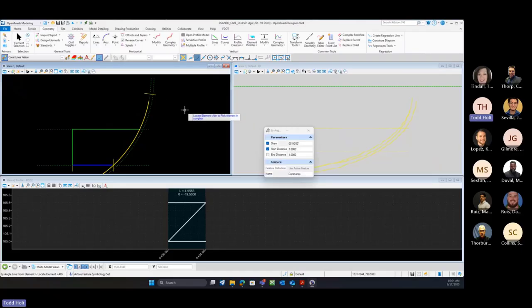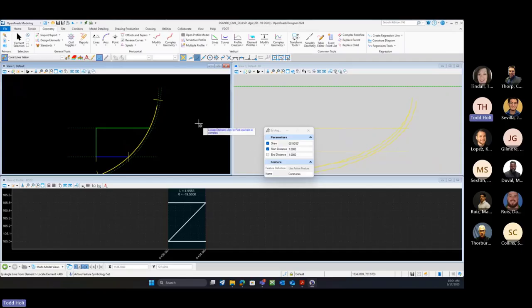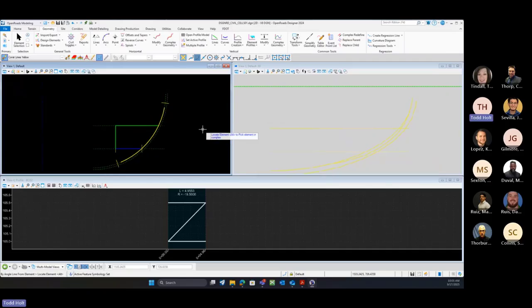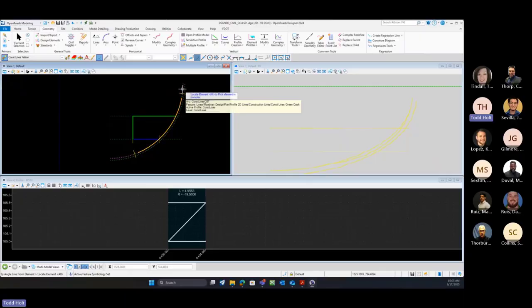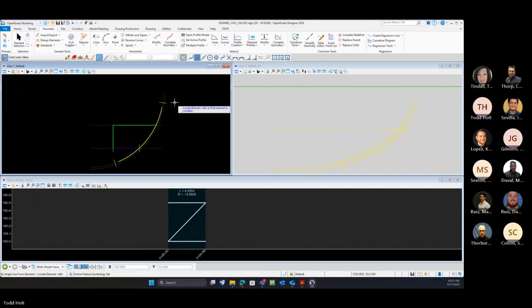So of these, another tool that we can use is the civil AccuDraw or delta station offset. On that one, I want this to be a certain distance from this intersection along this line or element to control this line. We're going to reestablish that. If I know what that distance is, and it doesn't really show from the details, under general tools, we can come to our civil AccuDraw. Toggle that on.